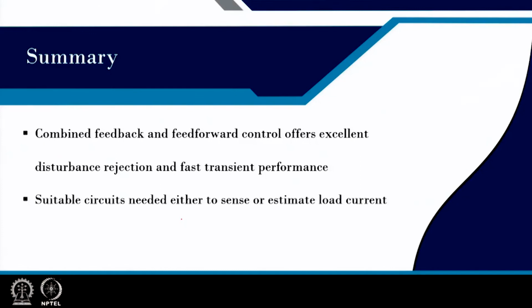So, you will not get the load feed forward from the inductor average value. So, you may need to sense the load current. In a buck converter, we can use a derivative action, or in digital control we can do a lot of estimation, and we can very accurately estimate the load information. In fact, in present processors, the power supply in a digitally controlled converter has something called the power management bus, PM bus, where there is data as well as clock communication. So if you communicate with the processor and understand the task requirement, you can estimate the load current. That information can be used to implement such an algorithm.